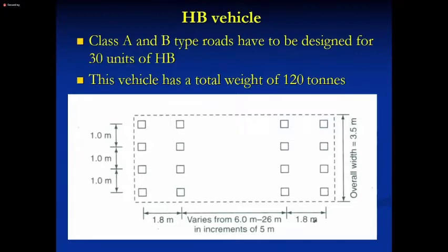And you can see the road has to be fairly strong surface, because if you take normal laterite soil, what is the strength? Maybe about 200 kilopascal.